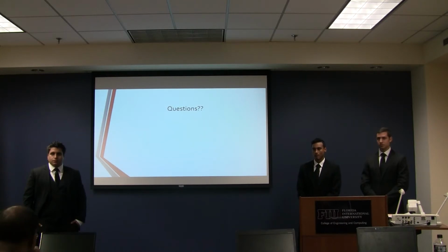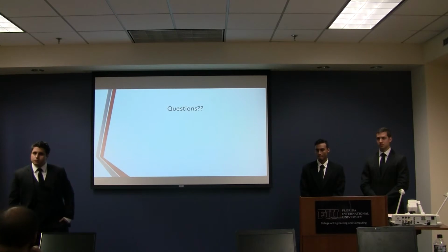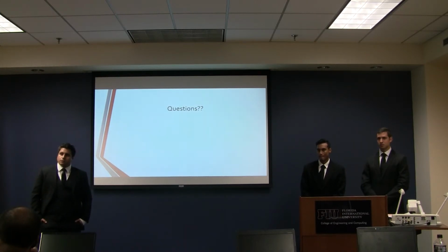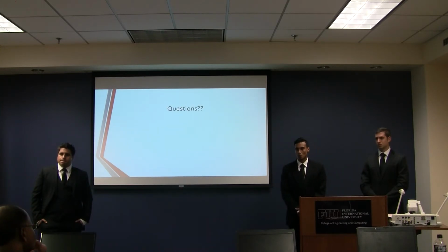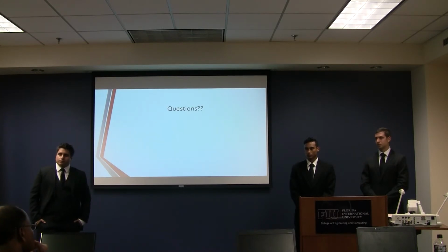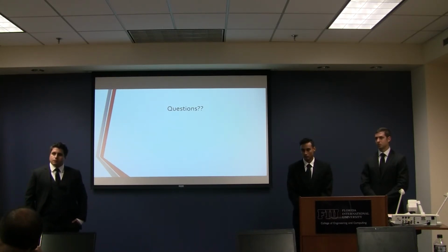One question I want to throw at you, because I saw the iteration. I like the idea of your iteration, but I suggest that you use something like a design of experiment to first figure out what variables you're going to change, and then set up a DOE to do that iteration pathway. Because if you don't, you may start iterating and it's never going to converge. You're never going to know where or what to change to have the most impact.